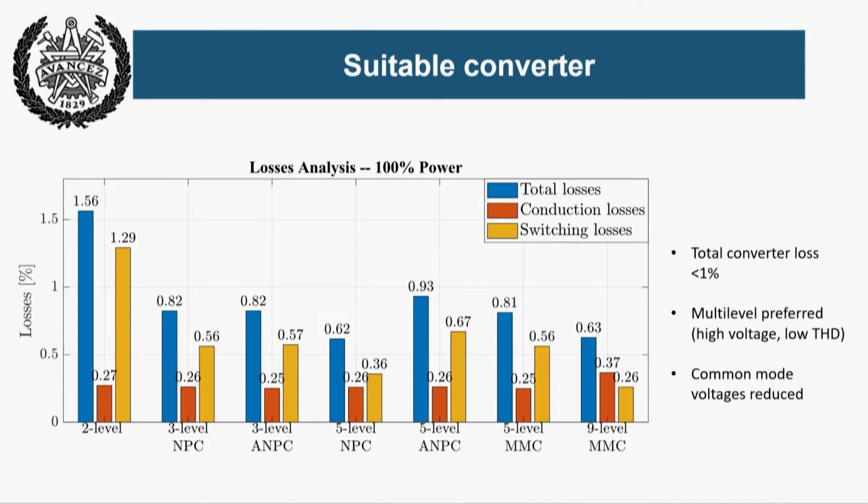And just to show one aspect, here you have a few topologies, the bottom here, MPCA, MMC and so on, and 2 level on the left there. So the 2 level is the one I showed on the previous slide, and then I think it was the 5 level on the previous slide, but they have investigated up to 9 levels and seen what efficiency you can typically expect from a machine. Now we're talking hundreds of megawatts, so losses are important.